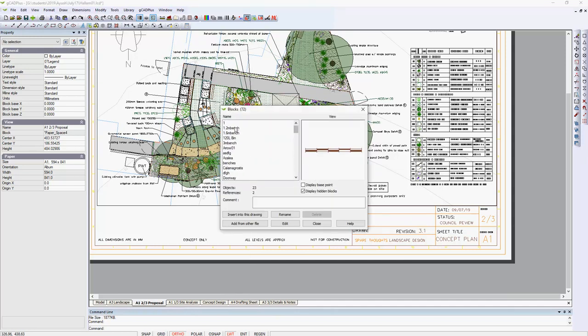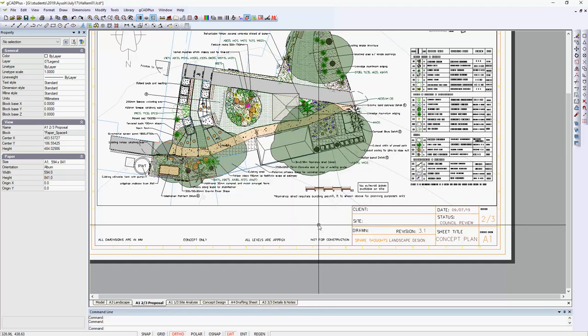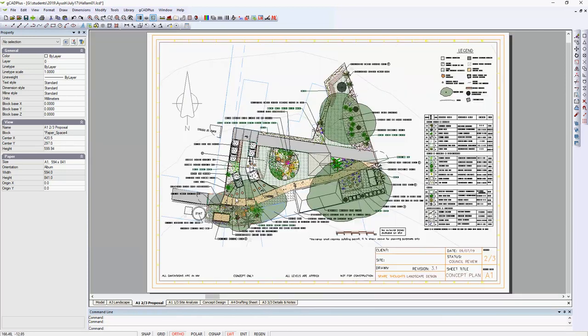I'm also in the habit of diving back in here and just scrolling down through to make sure that there are no other blocks associated with this drawing that are sitting on the shelf and can be deleted. And we'll do it again. It's called purge, so another 9 blocks have been removed. So just by some ordinary housekeeping, we can reduce the size of the file here. We're in the business of streamlining this drawing.